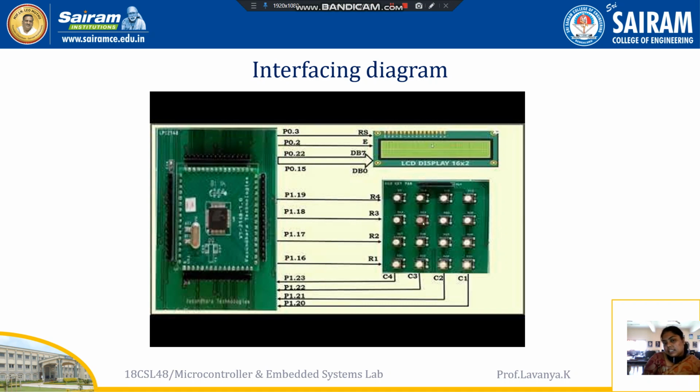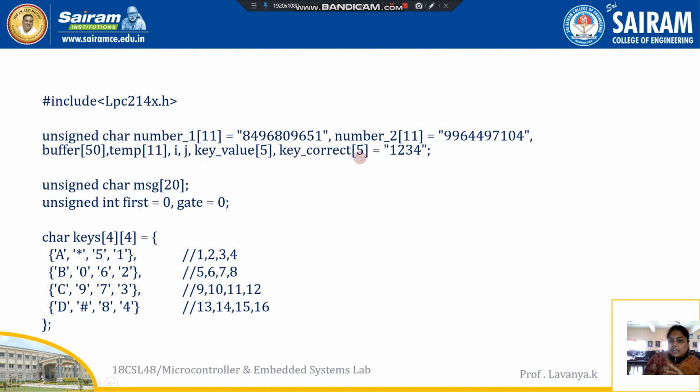See, this is the what. Okay, they have already made the connections between the ARM controller and keypad. Same thing, they have taken here also four inputs. Okay, some of the port numbers, and again 4 columns, like some of the port numbers. Okay, along with that again they have taken an enable register and RS selection register, and all the data, means all the 8 data lines.